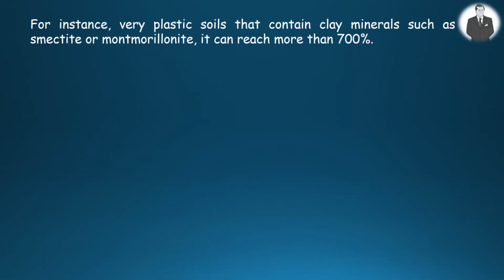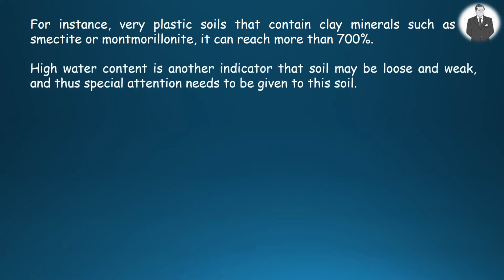For example, very plastic soils that involve clay minerals such as smectite or montmorillonite can have more than 70%. High water content is another sign that soil may be loose and weak, and that special attention needs to be given to the soil.